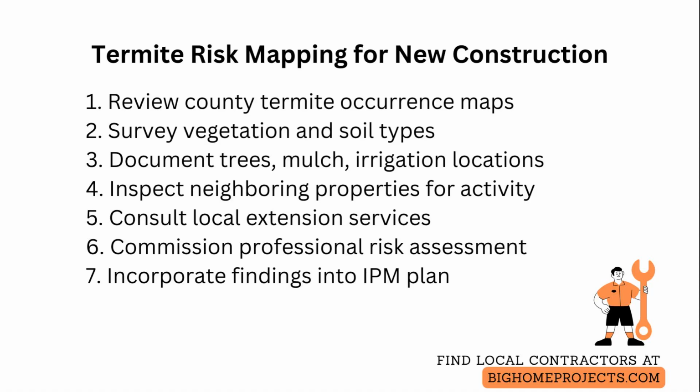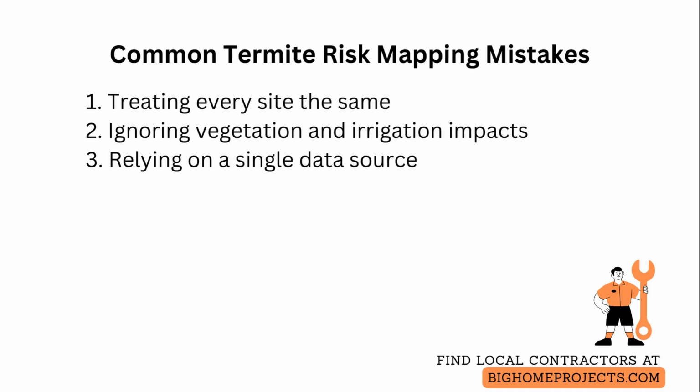Finally, incorporate findings into an integrated pest management plan that specifies foundation clearances, material choices, barrier and bait strategies, and an inspection schedule tied to the graded risk zones so builders can justify treatment intensity and designers can minimize vulnerable assemblies. Common mistakes are treating every site the same and over-applying a single method, which wastes money and can miss focused hotspots. Instead, grade risk across the site and match treatments to zone-specific needs.